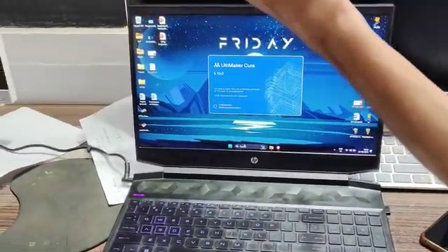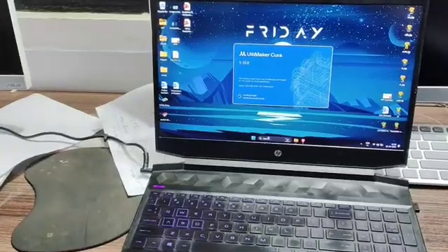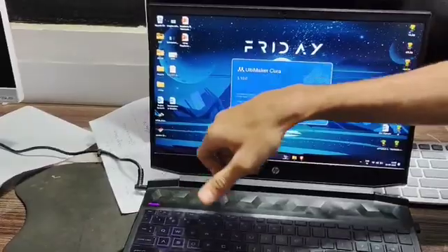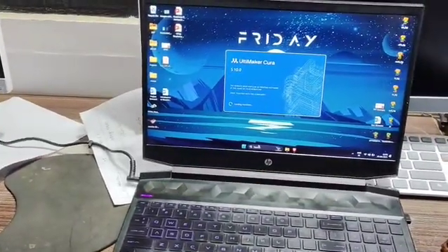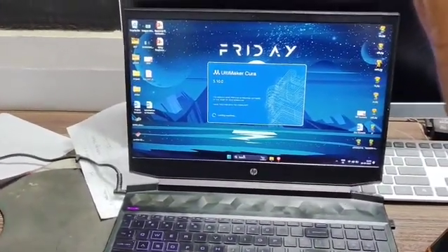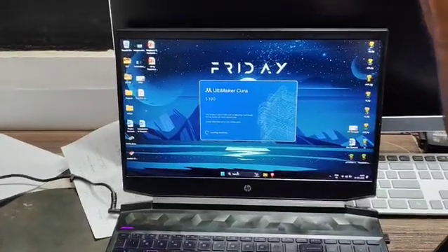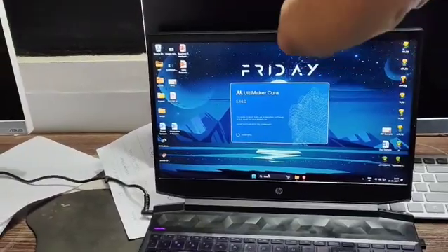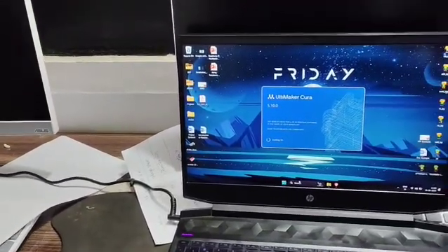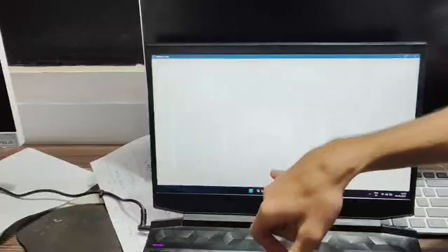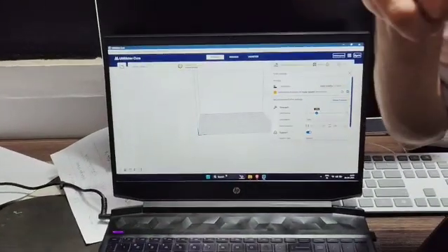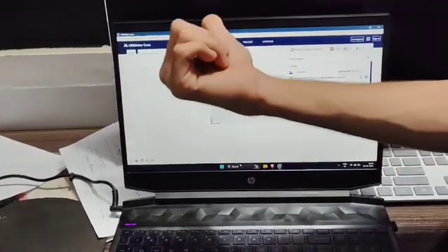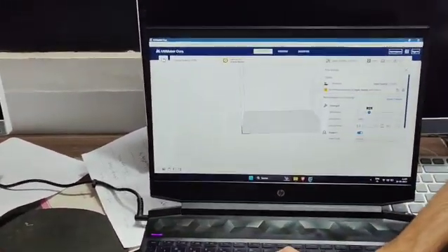So everyone design. Kishore, that was your 3D design. Now you have to open it in a Slicer app. The Slicer app will convert your design into G code. What is G code? Geometric code. It is something that your machines understand, that how it has to move, where it has to move. So your design will be converted into G code using another software. You design it in Tinkercad. You open it in any Slicer software. One I am using is Ultimaker Cura. And you open your design here.